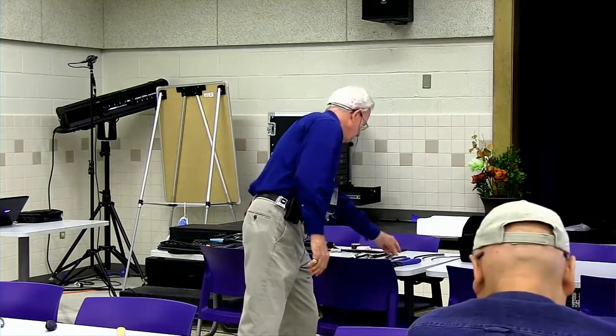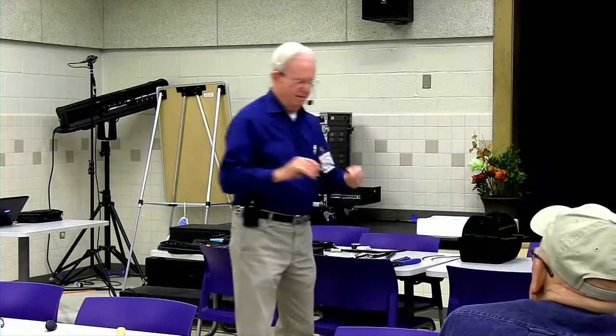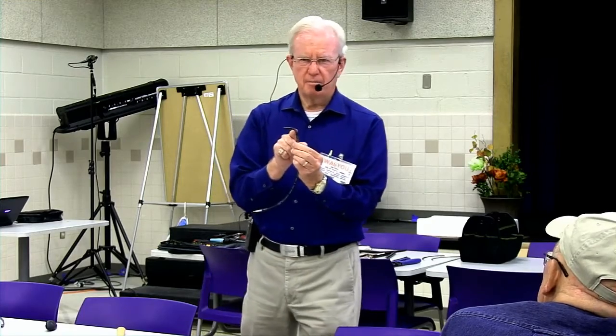That's how you figure bend radius. You don't want to go beyond that. You don't want to overdo bend radius, especially on this LMR double shielded stuff. If you go beyond the bend radius, I'll just do it because I have a lot of this. What we've done now is the center conductor is probably shorting or real close to that aluminum foil. Real close.